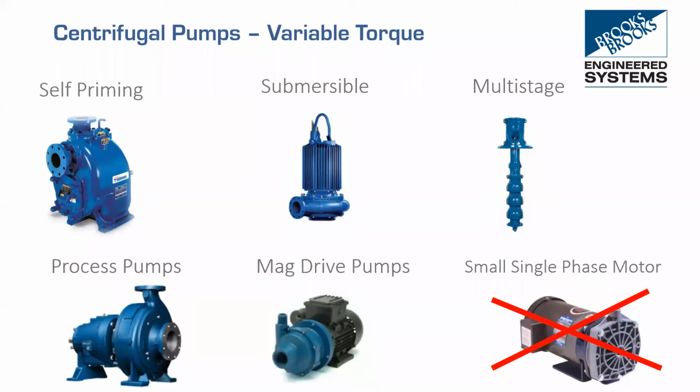If we've got a single phase power supply, what's often done is we feed a special VFD with 120 volt single phase power, and the VFD then converts that to 208 or 230 volt 3-phase power and connects it to a 208 3-phase motor. So when we're operating with a VFD, even if it has single phase 120 volt input, the motor always has to be 3-phase in order to operate the way that you showed on those previous slides.